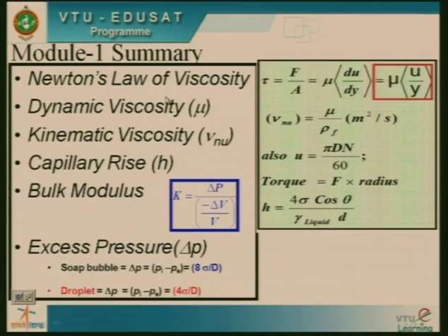The first law is, as usual, Newton's law of viscosity, which says that shear stress is proportional to shear strain, and the formula is shear stress, the shear force divided by the area, is equal to mu, which is the dynamic viscosity, times the velocity gradient du by dy.